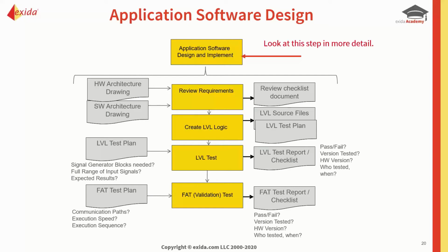The SRS should define the speed for each of the SIFs in which they have to operate. And they would normally split into the sensor subsystem, the logic solver, and the final element. So we have to make sure that we can meet the timing requirements. There may be sequencing. So for example, there may be permissives during startup or interlocks, and we have to make sure that those are also considered and tested.